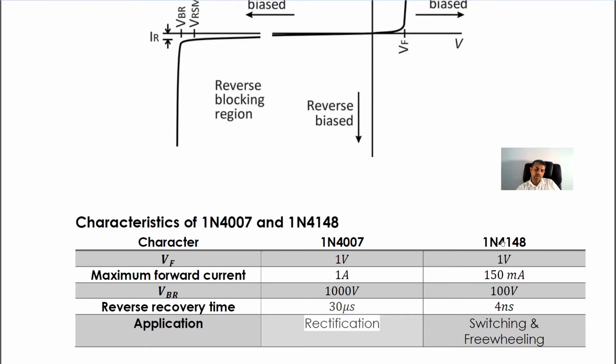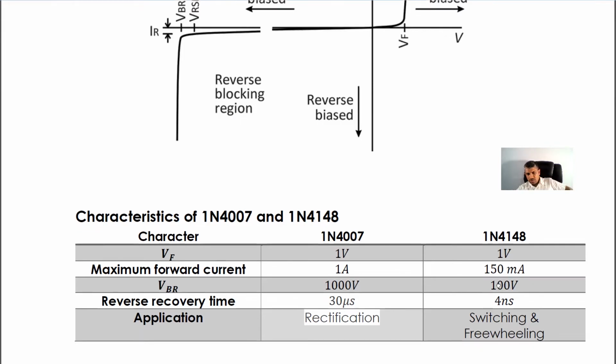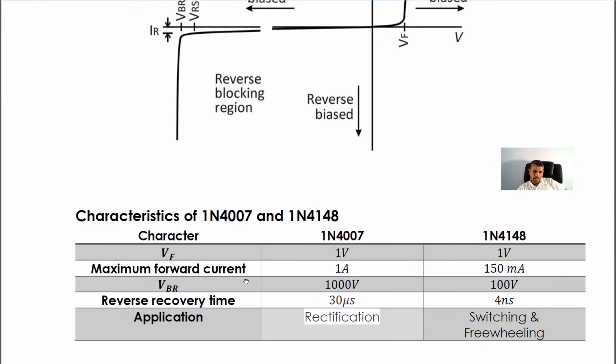But the 1N4148 has 150 milliampere of maximum current, you cannot send too much current. This is because this glass type one is sensitive, right?